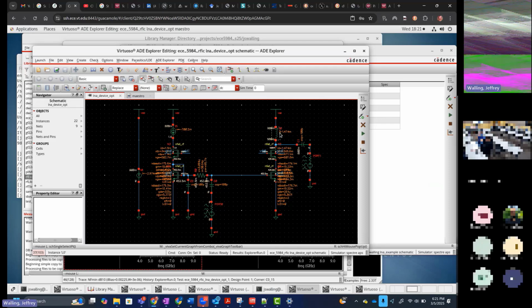And for right now, if I'm just trying to do some parametric studies of the device, I put a choke at the drain of the transistor, and then an AC short going towards the load. What is a choke and what is an AC short? You want the choke impedance to be about 100 ohms or more, or something like that. The AC short should be like an ohm or something like that. That keeps the AC signal wanting to go this direction and not this direction. You can make it bigger if you want. Won't hurt too much.